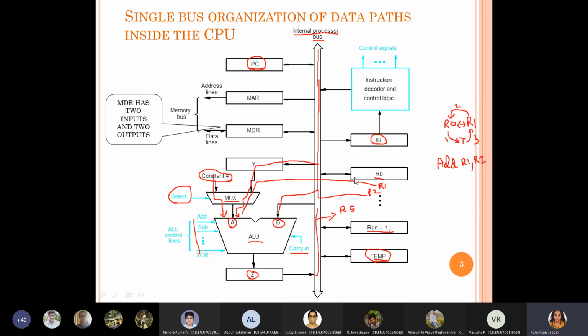So now all these are the basic flows within the processor, or within the controller, where either you transfer the data between the registers, or you increment the program counter by transferring its content to the ALU and store the incremented value back to the program counter. Or once you get the instruction of what operation needs to be done, you move it to the instruction register. All these data transfers take place within the processor or within the controller.